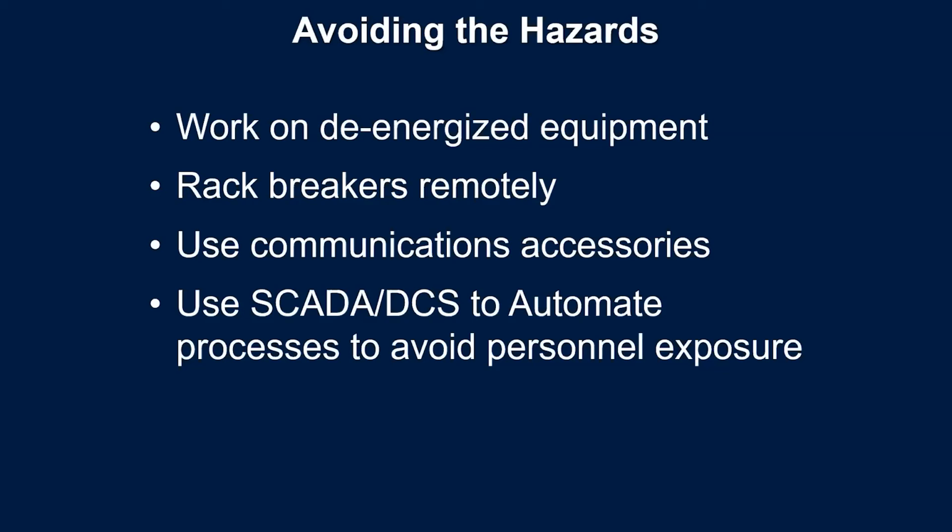And so if you think about it, taking communications one step further, a lot of these processes can be automated, because event retrieval, metering, these may be some things that you want to do on a regular basis, and these can be scheduled with automation devices such as an RTAC and software that goes along with it to collect this data at a regular interval, and then not have that human layer attached to this operation.